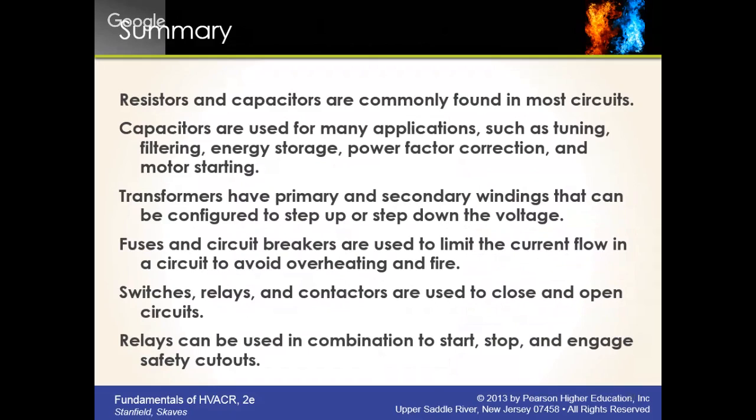Okay, relays, what are they used for? No load on the switching side. Switches are in the de-energized spot. Contactors are used for opening and closing larger loads, and the contacts on the contactor are going to be larger than on a relay.